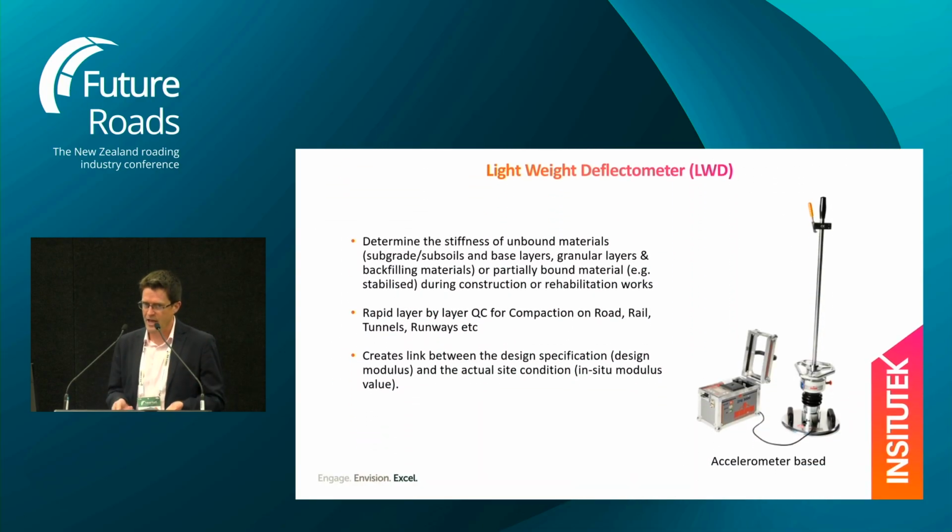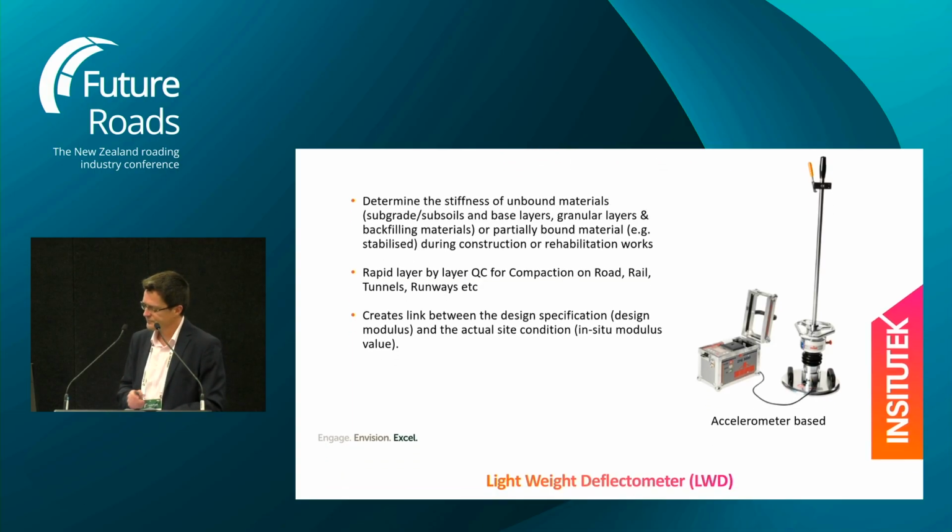This is a layer-by-layer compaction control tool designed specifically to enable us to get real-time feedback of how we are progressing with a stiffness-based assessment. We're measuring deflection and then calculating stiffness from that, and we can relate it back to our resilient modulus through plate load testing as well.